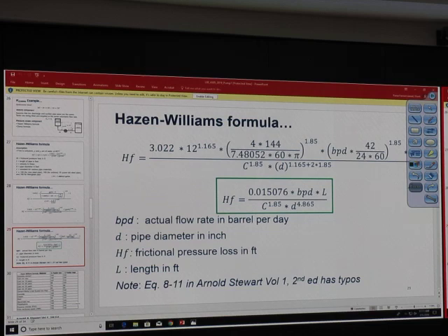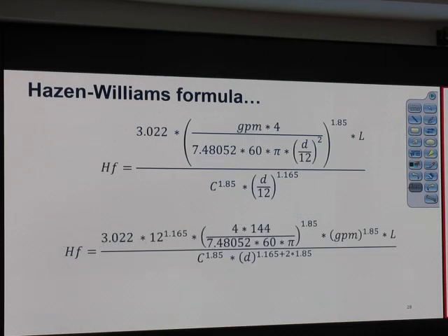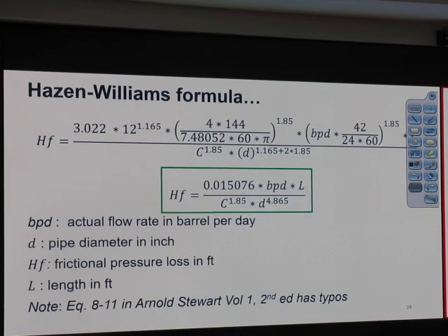All right. We will try to go through this pump and the calculation about the pump, and hopefully you find enough reason that we learn about this. On the Hazen-Williams equation, the restriction is that it applies to turbulent flow, water only, and water at the pressure and temperature that they derived it from. This is the final form of the Hazen-Williams equation.